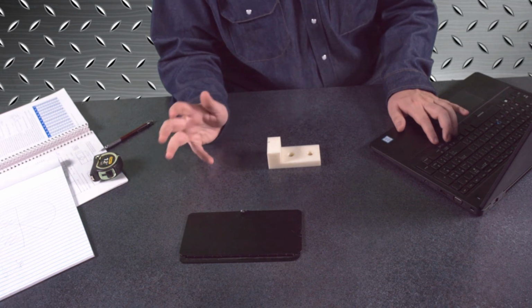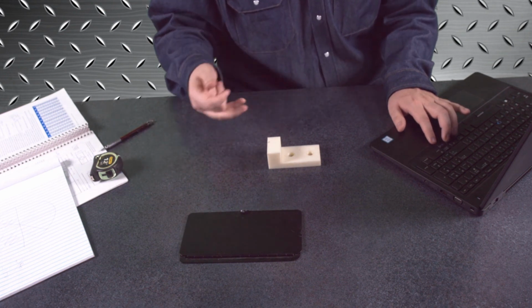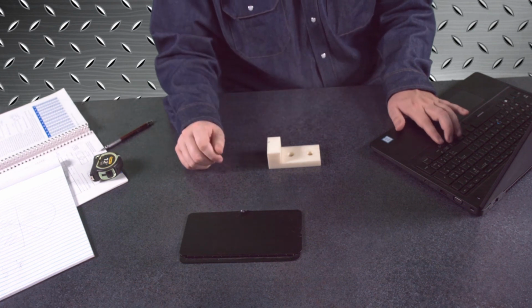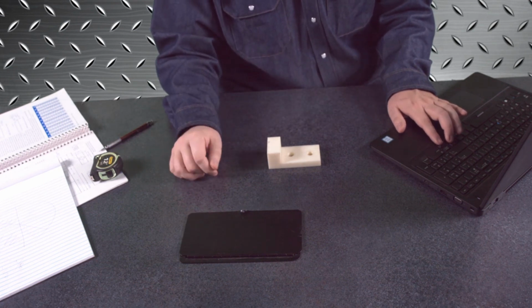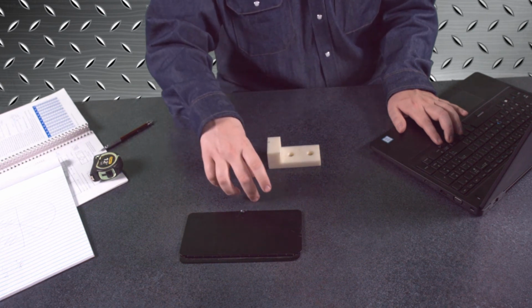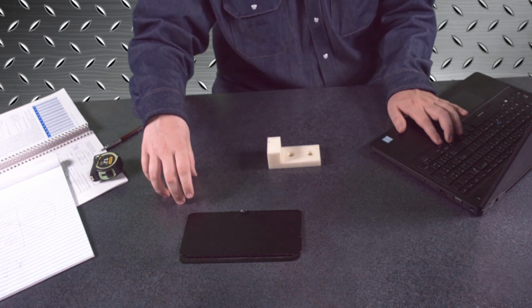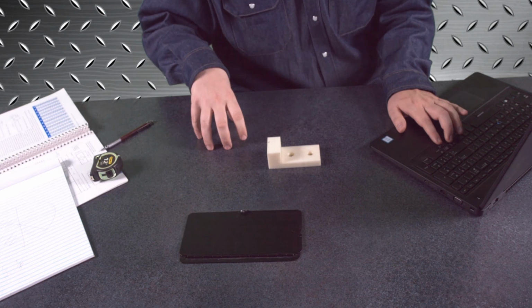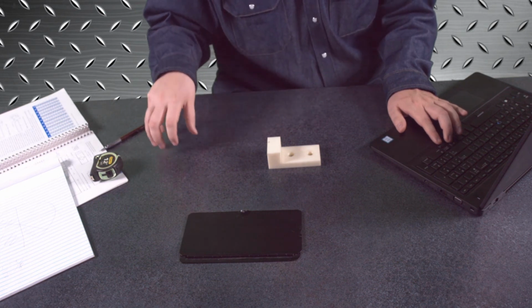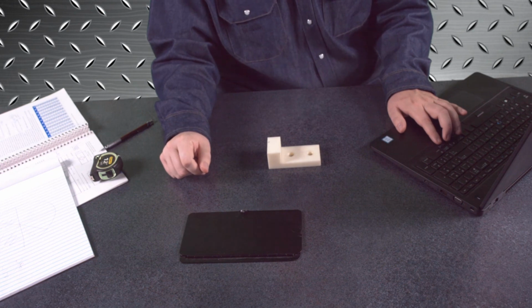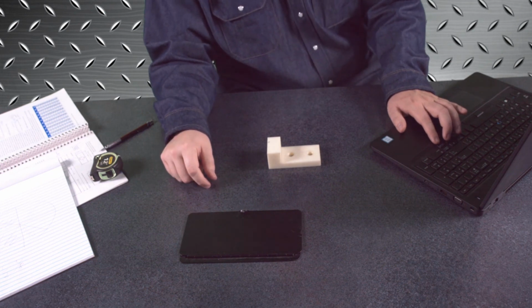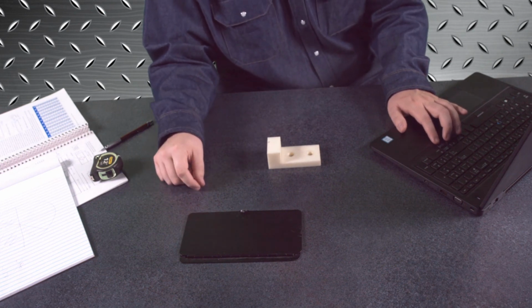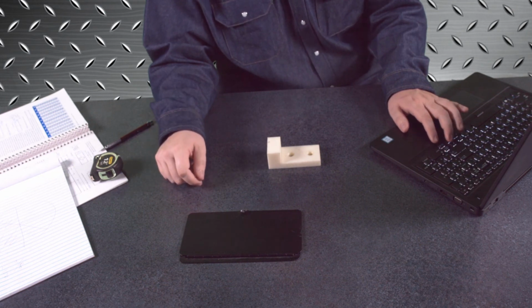Now, dual dimensioning can be expensive because it takes up more room on the print and it takes more time to convert all that and make sure it is converted correctly. But traditionally, you're going to have the US decimal fraction, and then below it, you'll have it in millimeters in brackets, or you'll have it to the side of it in brackets. So the first measurement you'll read will be in US customary, and the next measurement you'll read will be in millimeters or whatever metric dimension you're using.